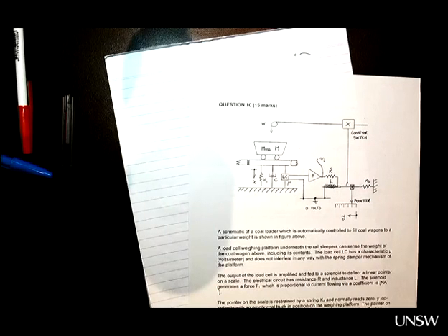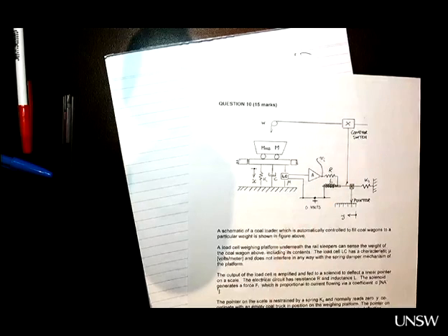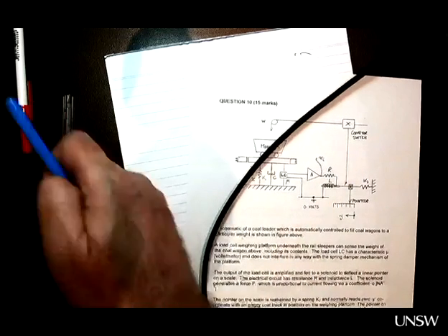Hi. So when you're trying to find your time constants, does your coefficient in front of s always have to be just 1? No, no. Your coefficient in s to the power of 0 has to be 1. So what I did here, a bit clumsily, is I created this to be 1 and this to be 1.